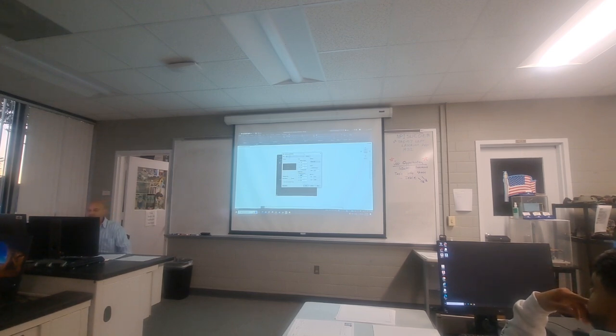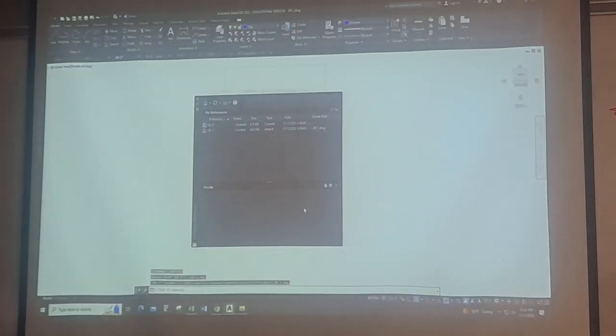So anytime you're doing something like this to where you're mating one drawing to the next is very important. 0, 0 is your insertion point. Sometimes that means you're drawing it, like I said, you're not drawing around that little XYZ 0, 0, 0 point. You're drawing off in space so that whenever it gets dumped into that virtual model, it falls right in place where it needs to be. So on this one, I'm gonna make sure to set that to 0, 0. That's the only change that I'm gonna make, okay?